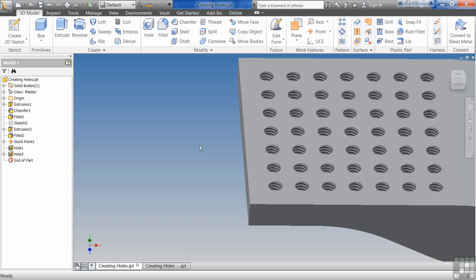And the reason is because the mathematical overhead of calculating a helix going through that hole is huge. Just this number of holes here, if these were actual cut into the part, would use as much memory as a 4,000 or 5,000 part assembly. So you definitely do not want to add threads whenever possible. You don't even want to add the bitmaps, but there really is no reason to ever cut the threads.